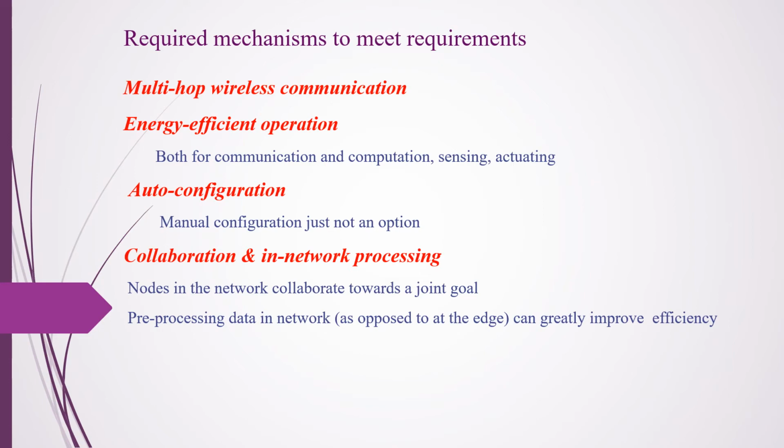General wireless communication takes place in a direct manner between a sender and a receiver, but it has a few limitations. In particular, in WSN, when we need to cover a long distance, we need to have high transmission power. The use of intermediate nodes as relays can reduce the total required power. Hence, we are going to go for multi-hop communication, which will be the necessary ingredient.